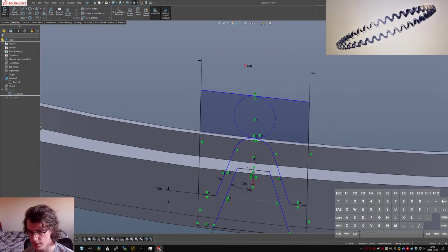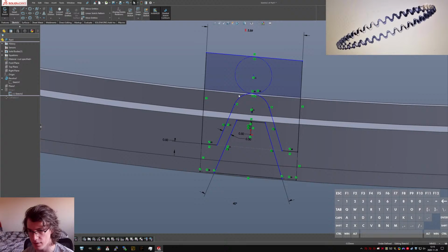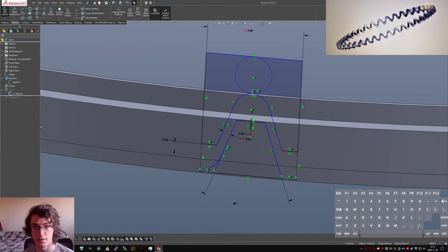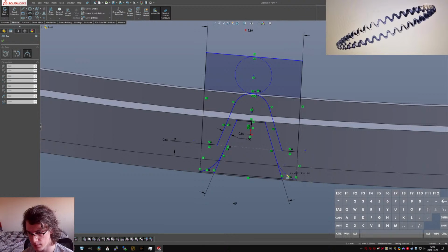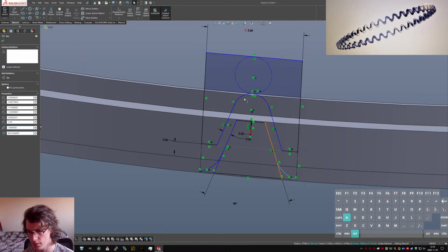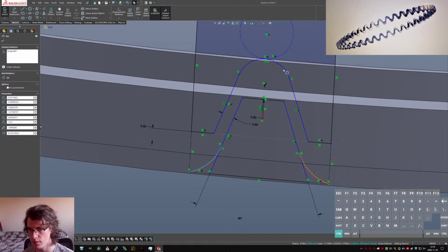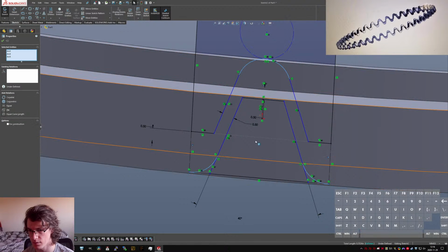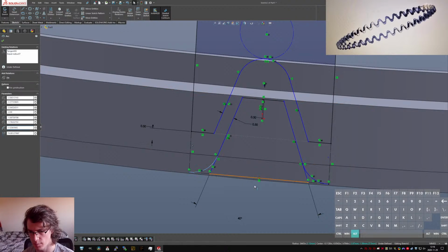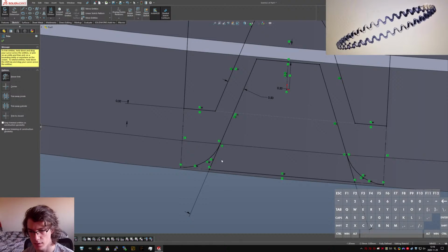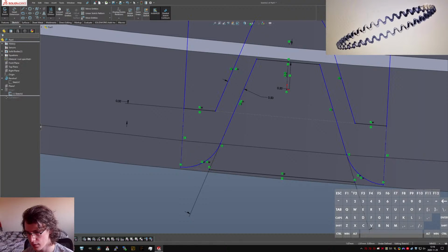And okay, so now we've got some kind of weird size variability there. The next thing to do to fix that is edges over here and over here to make those tangent. And we're going to make them all equal to this guy, this sort of master one up here. I'm also going to make him tangent down here, which locks everything into place. Then I can make those cuts, bring that out there.